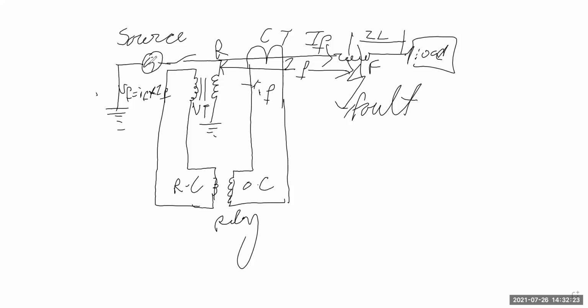As shown over here, it starts with the source of electrical supply, that is the alternator. Then we measure the current through a current transformer, which is used in series with the line. Similarly, a potential transformer is used in parallel with the transmission line to measure the stepped down voltages. These two parameters are fed to the relay for evaluating the impedance of the transmission line.